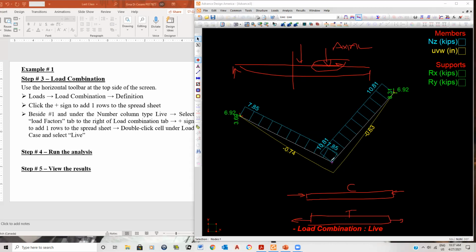Now here, when I put a force like this, in order to resist that force, these members are pulling this way, and therefore you have tension here. So in other words, these members are all being pulled together, and the way the program tells you that the fibers are in tension is because it gives you a positive value there. That's what the positive value means. It's just to tell you right away, all my fibers are being stretched. Okay, and since steel is being stretched, very good. That's how steel likes to be. The best way steel can be used is by always having it act in tension.